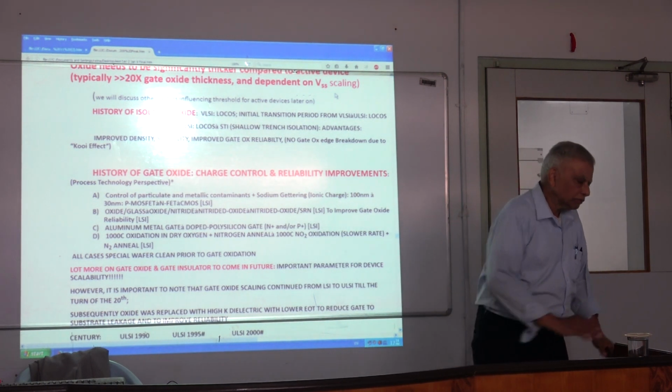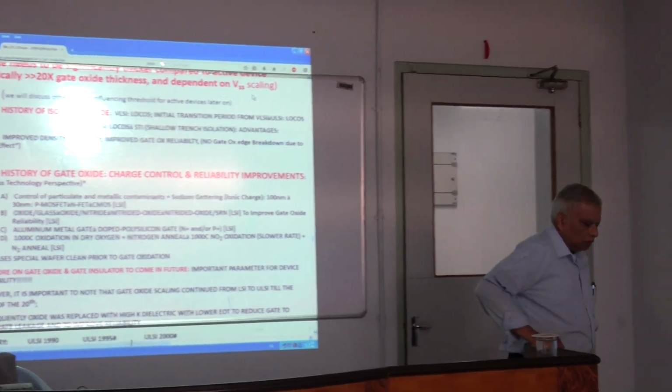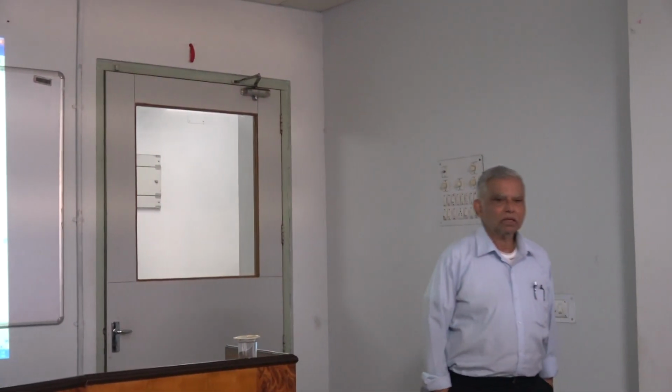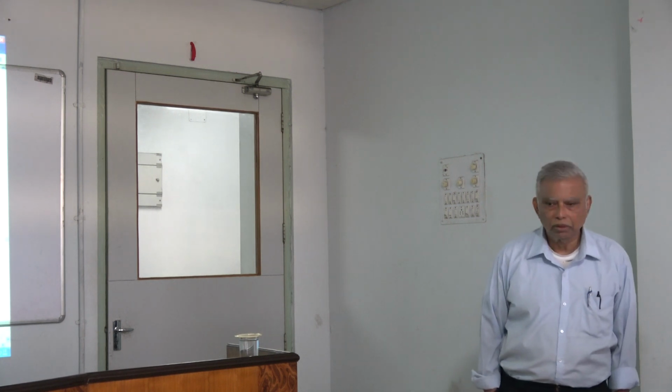It's no good for CMOS or field effect transistor for a different reason. That someday I will have a chance to talk to you on that. But we reliably built non-volatile memory devices with 15 angstrom interface oxide, reliably. And the technology was qualified, although we never made the product.